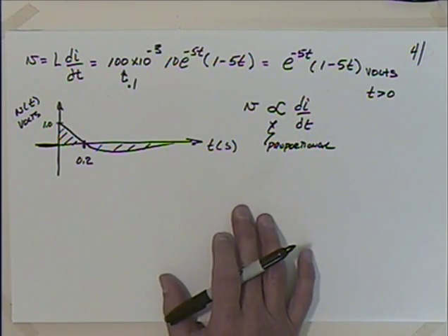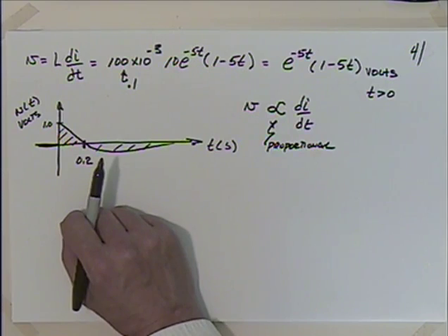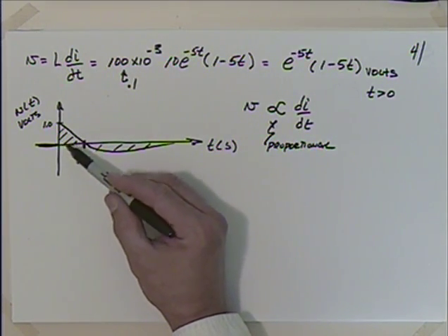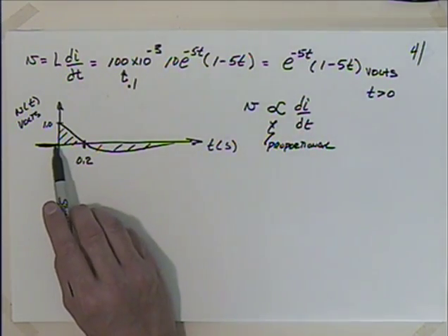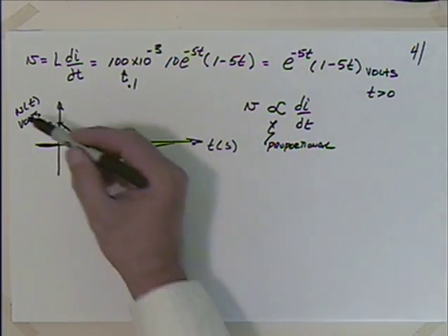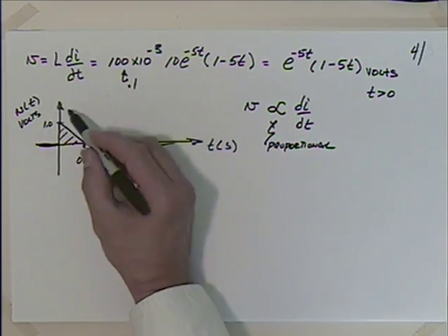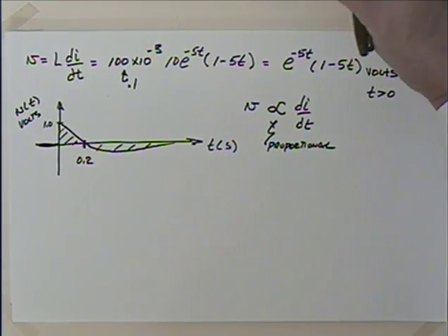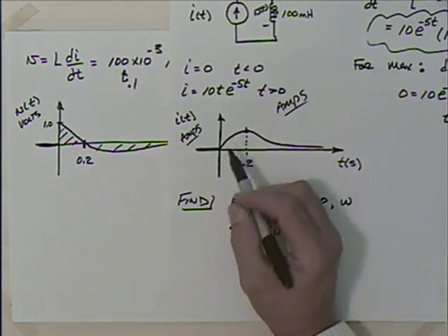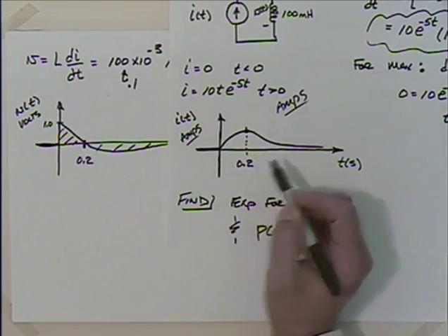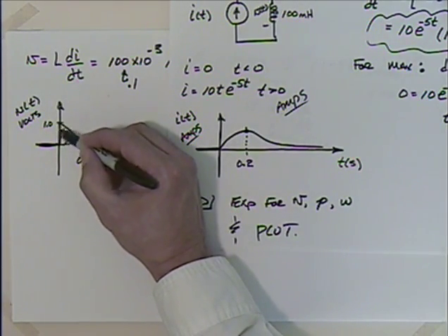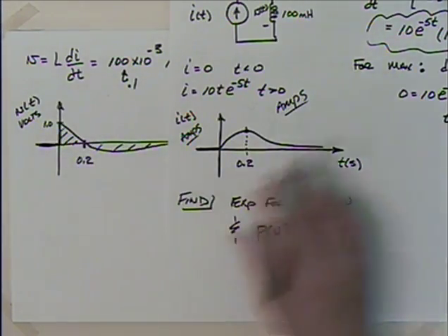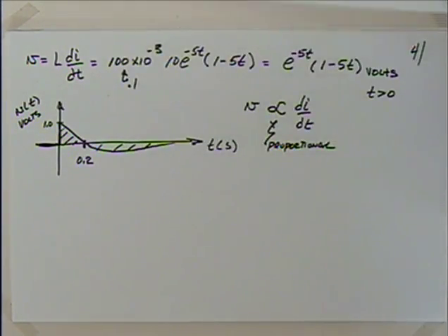Now, what do we learn about the capacitor? We couldn't have an instantaneous change in terminal voltage, right? Would this be an acceptable graph for the capacitor? No. What if I'd mislabeled these? What if I was trying to sell you this graph here for the inductor as current? Well, we know that the current in an inductor can't have an instantaneous change. Does the current have any instantaneous changes? No. Could we tolerate this discontinuity here if this was a current graph? No, we could not. So I'm glad this is the voltage graph. I'm glad it's an inductor because it's behaving like it should.